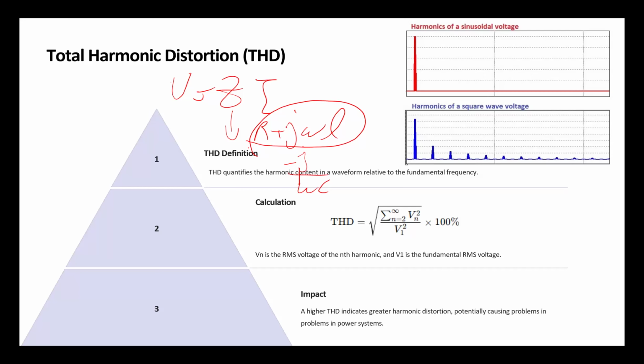When we have harmonics, we use PWM to ignite our switches. We can manipulate the parameters in PWM to change the level of harmonics because we are changing the waveform. Now, if we wanted to only limit or mitigate the higher frequencies, and that was our only goal, we could manipulate the switching to reach it.